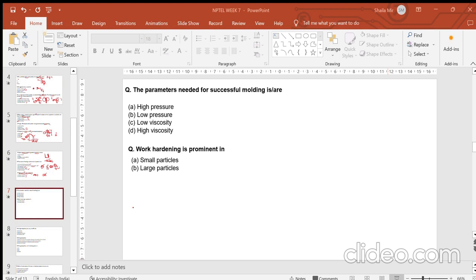But if the orientation of the particles is different, or if the edges of the particles are angular, for example, there will be friction between the particles, and that will not allow the pressure to be the same. So it depends on multiple factors, and it cannot be generalized how much difference there will be between the pressures. It will depend on your material.